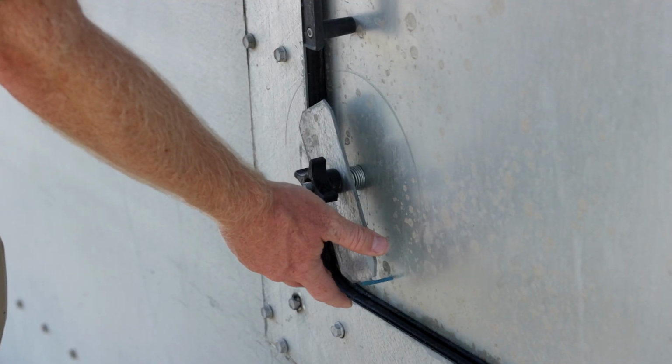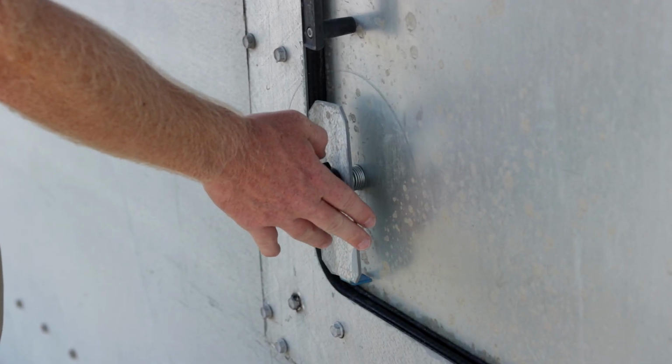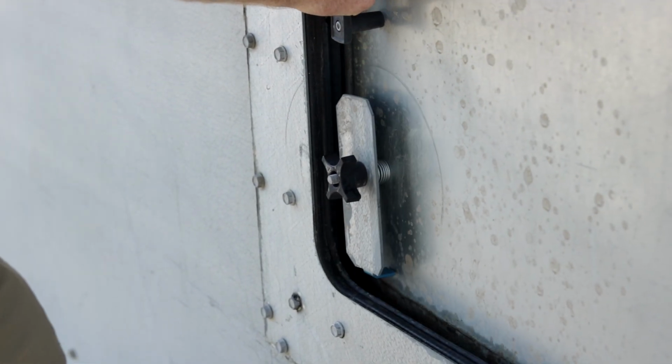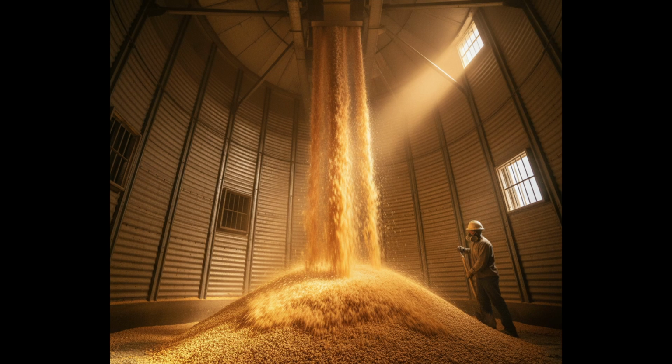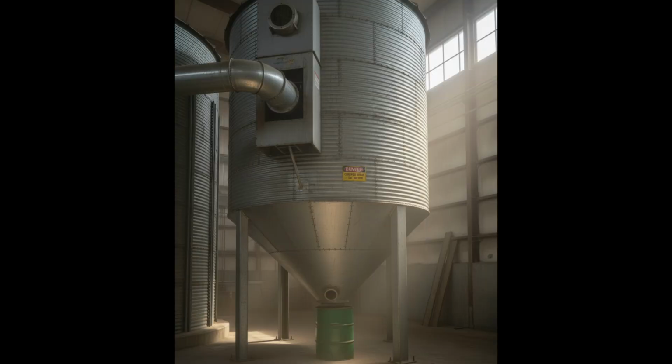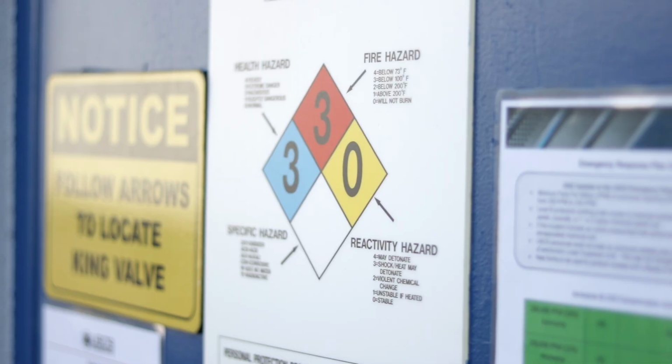The space has the potential for containing a hazardous atmosphere, such as a toxic environment caused by ammonia, oxygen deficiency, or flammable atmospheres. It contains a material that has the potential to engulf an entrant. It has an internal configuration such that an entrant could be trapped or asphyxiated by inwardly converging walls or by a floor which slopes downward and tapers to a smaller cross-section, or contains any other recognized serious safety or health hazard.